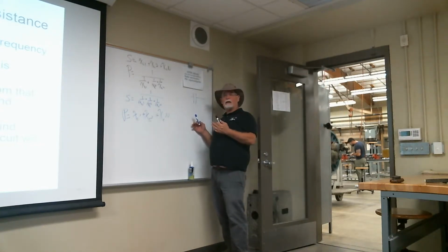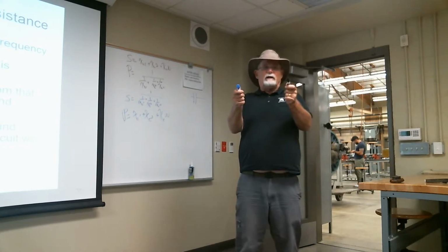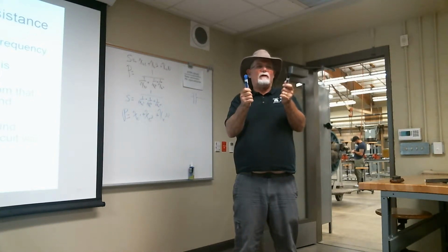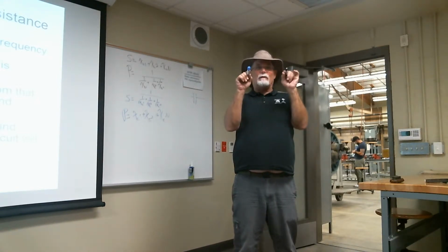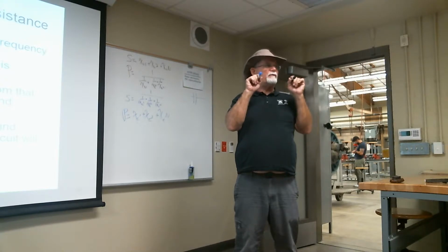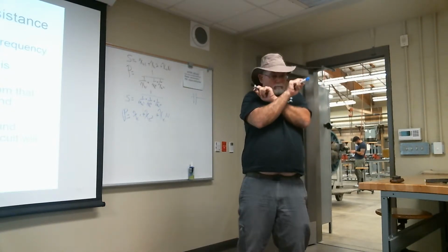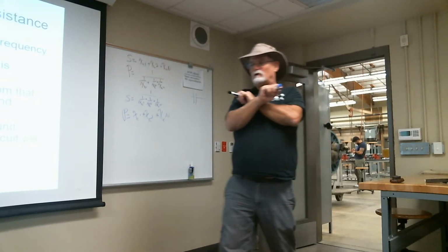Or, in this case, voltage is now going to lag behind the current. As soon as I touch the capacitor, it sees almost no resistance to that initial current. At the point that the voltage gets to maximum or battery voltage, current comes to a stop, doesn't it? And then when I reverse the leads, boom, voltage drops because the power source can only put out so much, current immediately starts going.